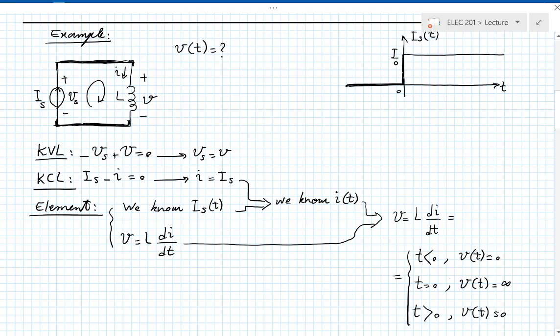Now, typically what happens, if you're lucky, is that a wire breaks or the current source breaks down without a hazard. But that can't be guaranteed. So you should never do this. But if you actually forced things, if you did this on paper, like we did here, you would really require an infinite voltage at that moment. So your voltage is basically a delta function.